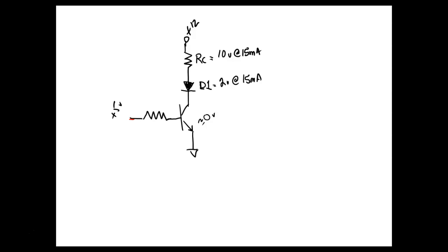So knowing Ohm's law and knowing Watt's law, especially Ohm's law, because even though I don't write it down, it gives us an indication of how voltage affects the circuit and how current affects the circuit. If you understand that, then you don't even have to solve it. You know if voltage goes up, current has to go up, the resistance goes up. So we know that R is equal to V over I. That's why on your formula sheet I don't give you R, I don't give you Ohm's law, I don't give you Watt's law.